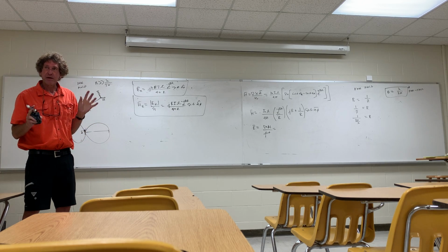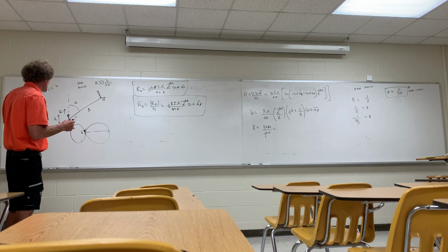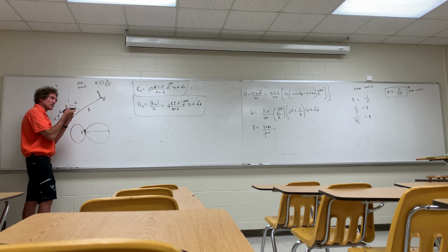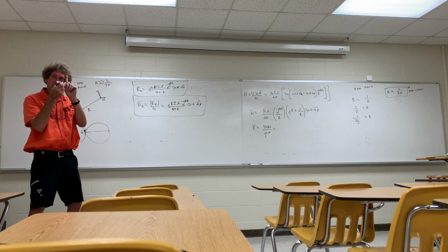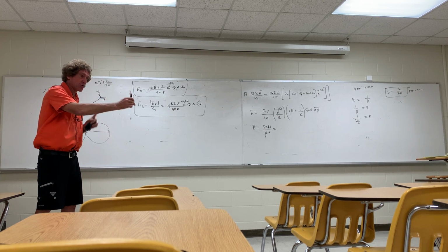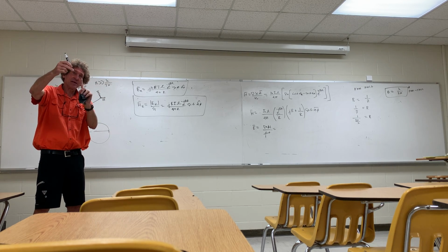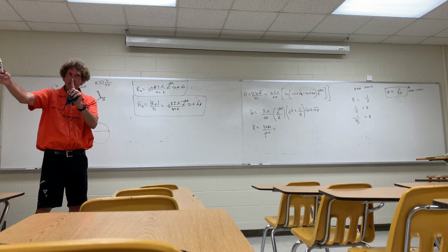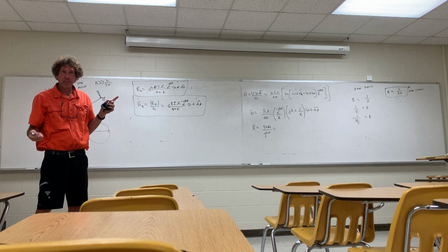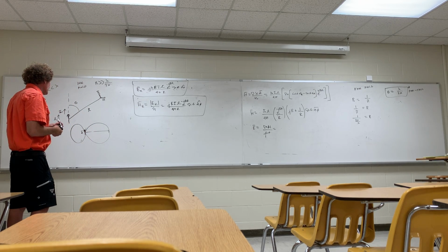Makes sense to everybody? Now here's why that's so important. When you have a short dipole antenna, and you're going to see it's true for long dipoles too, the maximum field radiation at a given R is always perpendicular to it. If the current's going this way, at 90 degrees to that is where the peak E field is radiating. So it's radiating a maximum at the equator, you might say. If you mount this on the Earth, at the actual horizon is where the E field is a maximum. It's a minimum straight up or straight down. There is none. It'll help you visualize what's going on.